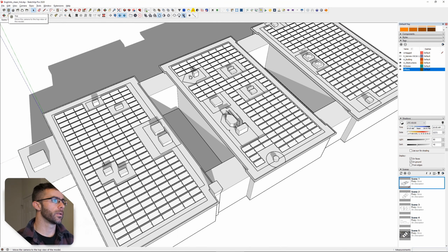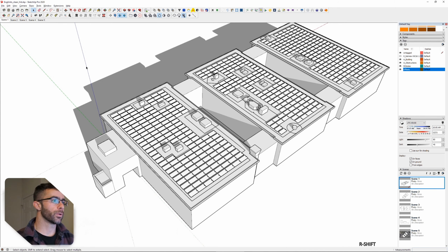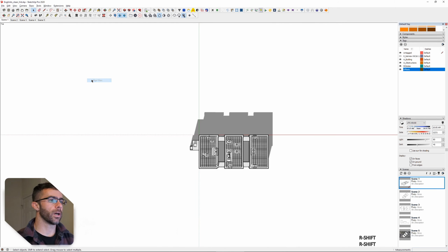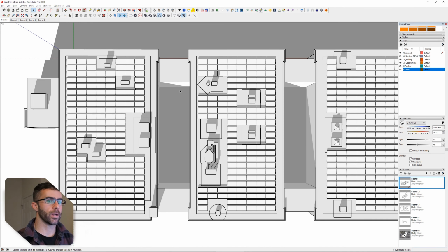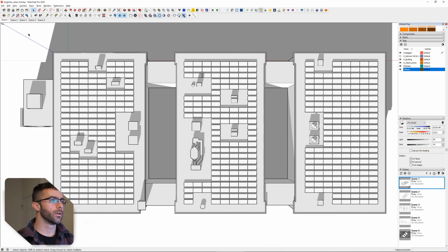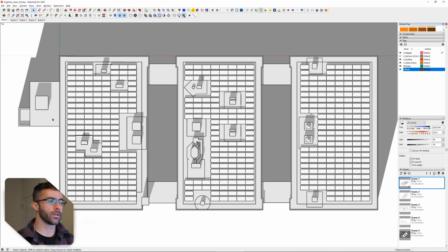So that's an easy way to get a good clean view. You can right click on your axis tool and say align view. Beautiful, and nice and square to your axis. Could even change to parallel projection, and that gets rid of parallax from your perspective view, which is kind of neat.